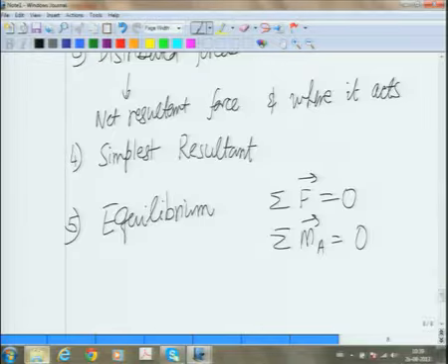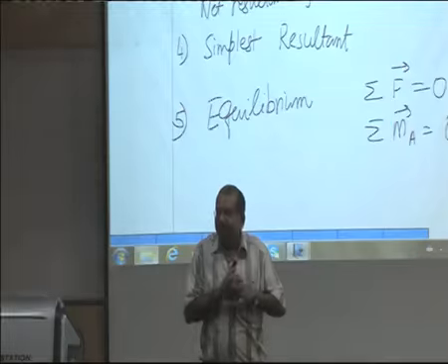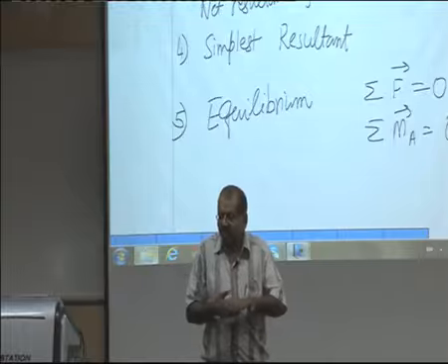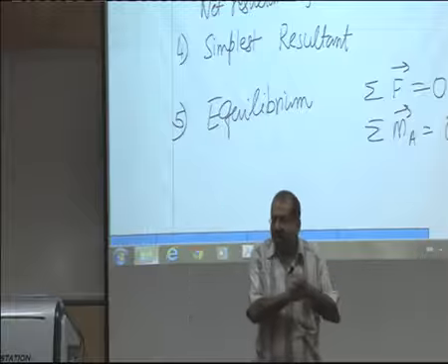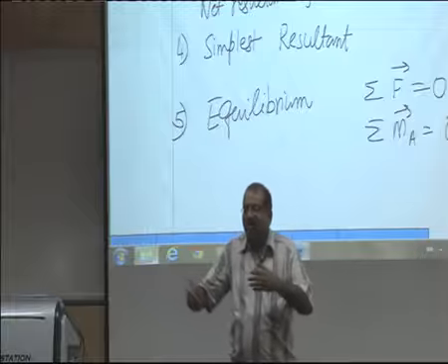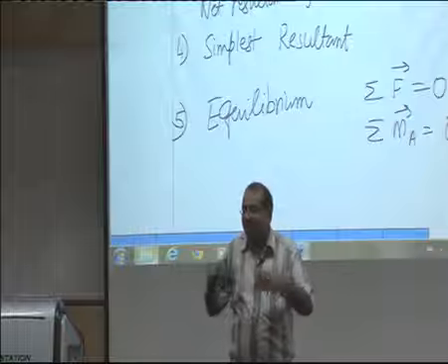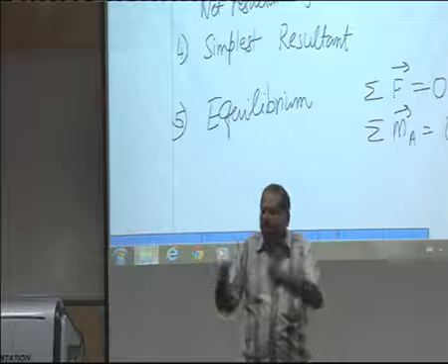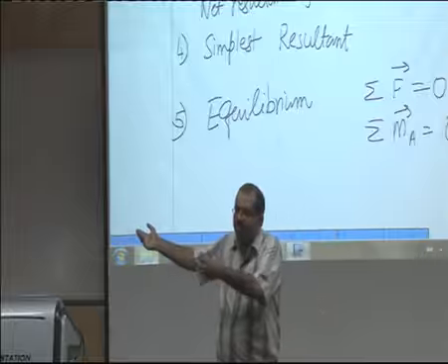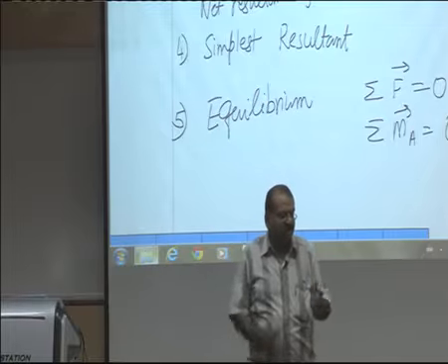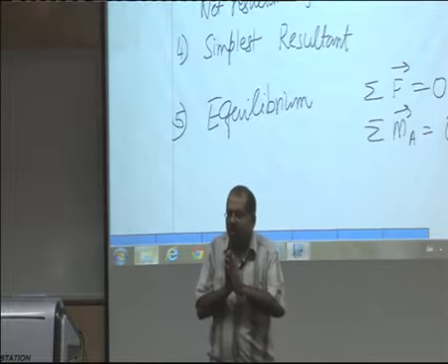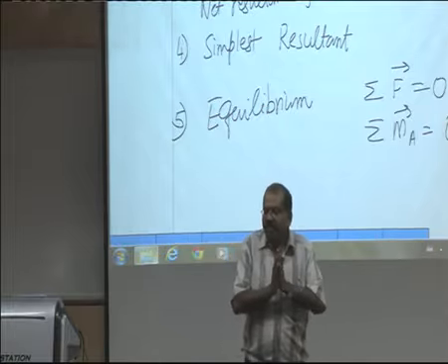Also we learned the concept of a two force member. When we did this, we also learned the concept of two force member. I did not specify or lay too much emphasis on three force member. Your textbook does a bit of it. In fact, even when you see the problems on friction, in some of these the solution which is given will say that all the three forces have to pass through the same point, and that is how they work out the solution. But you can use sigma Fx is equal to 0, sigma Fy is equal to 0, moments is equal to 0 to get the same answers. You need not use the concept of three force, or you can use it, it's up to you.